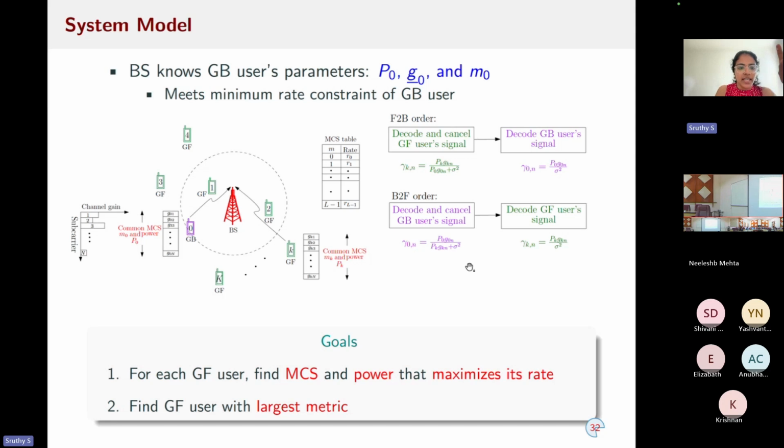Again, here we are dealing with frequency-selective channels, and we will have a vector of SNRs or SINRs. To deal with this, we use the EESM method, exponential effective SNR mapping, which maps a frequency-selective channel into flat fading.